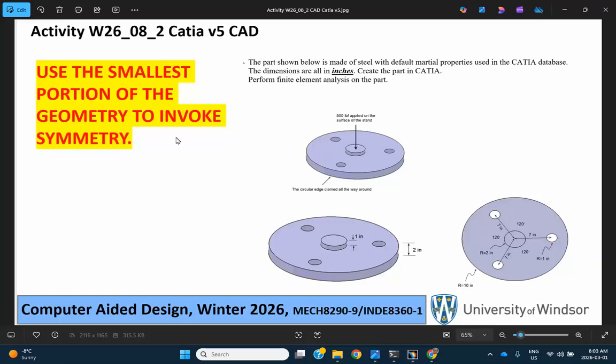The full model, the 1/3 model, which is going to be a 120-degree sector, either like this or like that. It makes no difference. And finally, the 1/6 model, which is exactly what I want. If this was a test problem, that's what you have to do. You don't have to do all of them. If you want to start with the 1/6 model, generate it, solve it, and upload it as your work on the test, that's perfectly acceptable. But I'm showing you these because I want to make sure that you don't make a mistake of overriding things by chance.